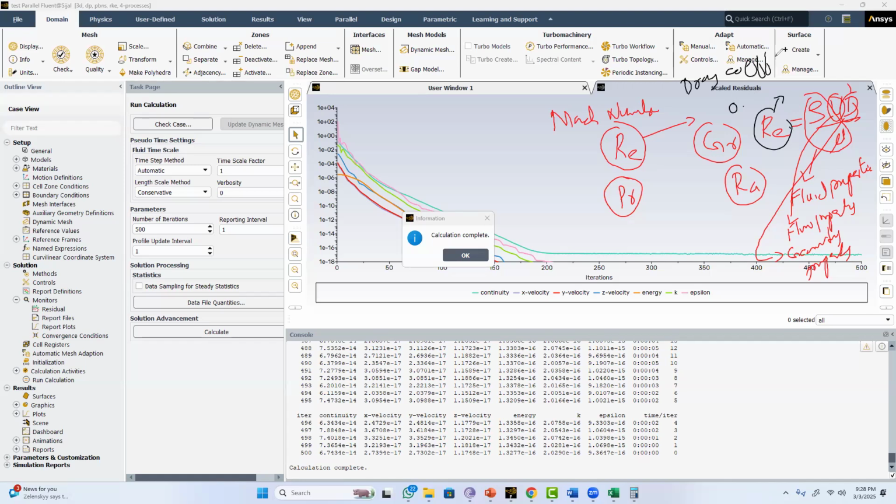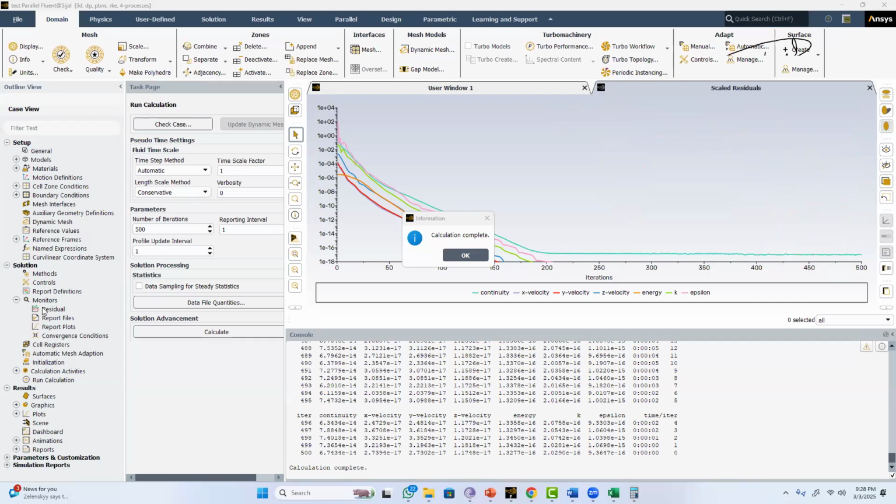I'm not talking about drag value, I'm talking about drag coefficient. Non-dimensional values should be the same. Dimensional values will definitely vary. For a large craft, the drag force will be higher. For a small craft, the drag force will be lower, but the drag coefficient will remain the same. If you measure the non-dimensional value, that's the point here actually. Okay, this is the whole story. So this answered your question.